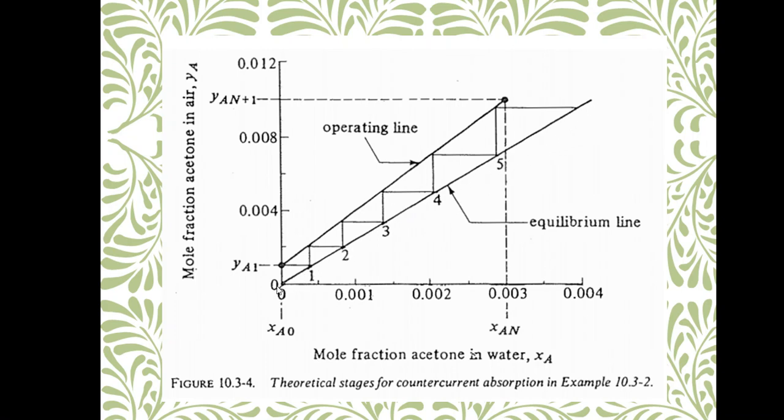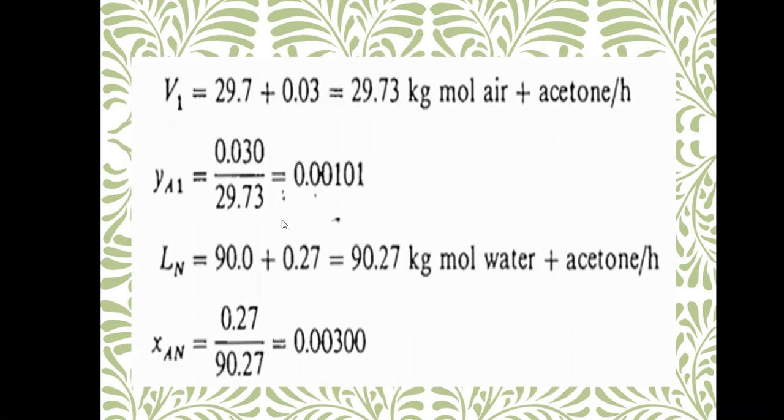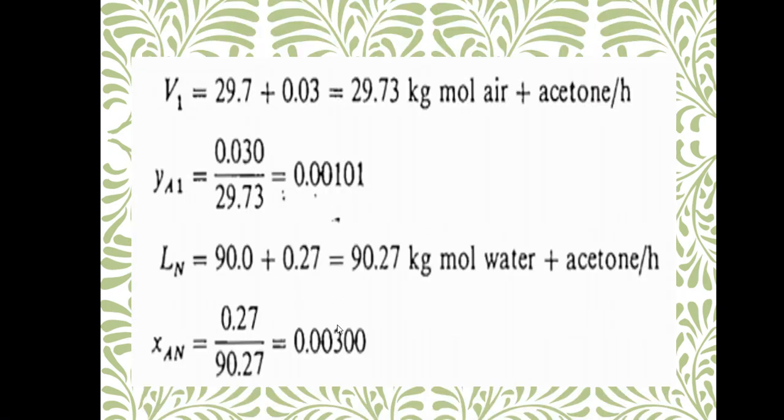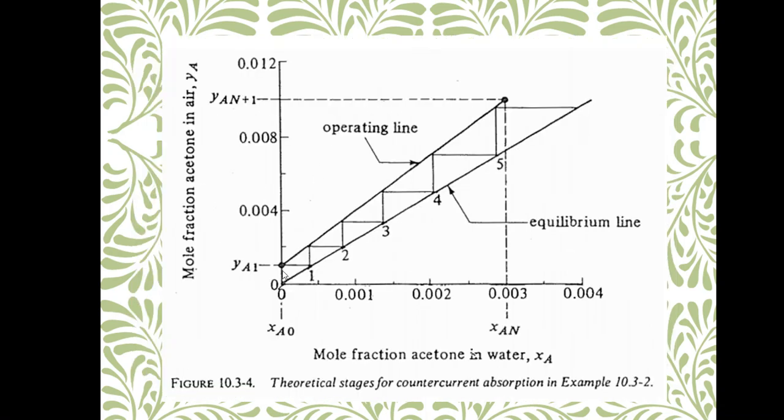A table expressing the relationship of x and y, whereas this operating line is above this equilibrium line because this is gas absorption. And the way you plot it is you use the given mole fractions. There are two mole fractions given, the 0.01 and the 0, and these two we have determined in the previous slide. So you pair them, that way you will be coming up with the operating line for this gas absorption process. And this will be the graphical procedure.